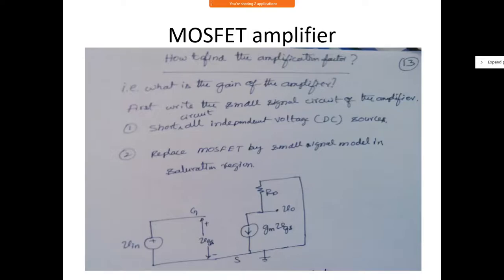Short circuit. It is not short all. It is short circuit all independent DC sources. What is the purpose? Why are we actually making all independent DC sources short circuit?